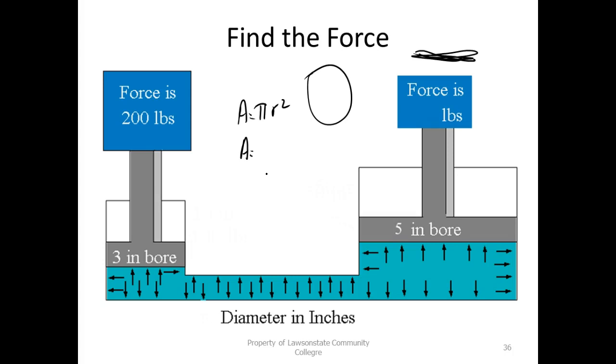Of course, that would come into play if I design cylinders, because I can't push 2,000 pounds with a little thin piece of plastic. So the thickness of the piston would determine how much force it can handle, right? But especially in pneumatic systems, low pressure, you're not concerned. So a good example of a plastic piston is a syringe, and so your doctors use that.